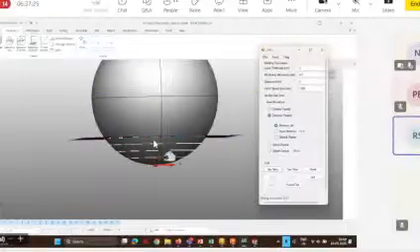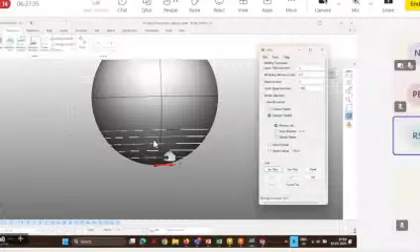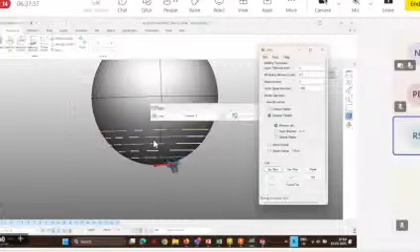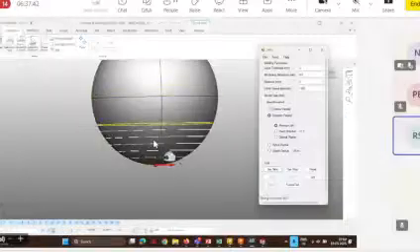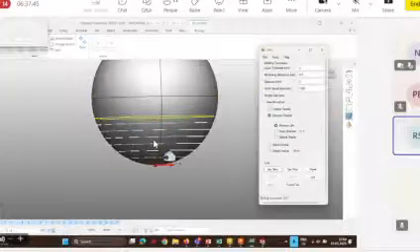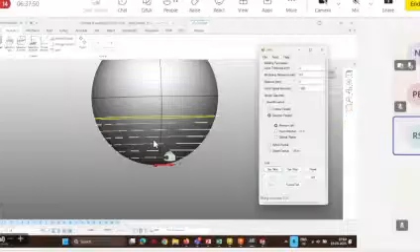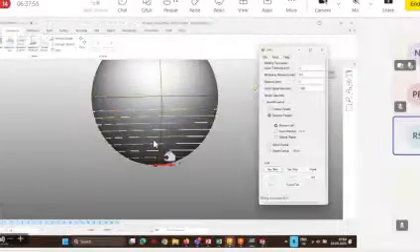So all the slices are being generated. Not only generating, and one thing that in the previous session I showed towards the end is that because of the lower number of points in the slice contour, it creates issues during toolpath generation. So to eliminate that, we are just repointing: we select the slice and increase the number of points in this curve, so that no such issues will be there in PowerMill basically.